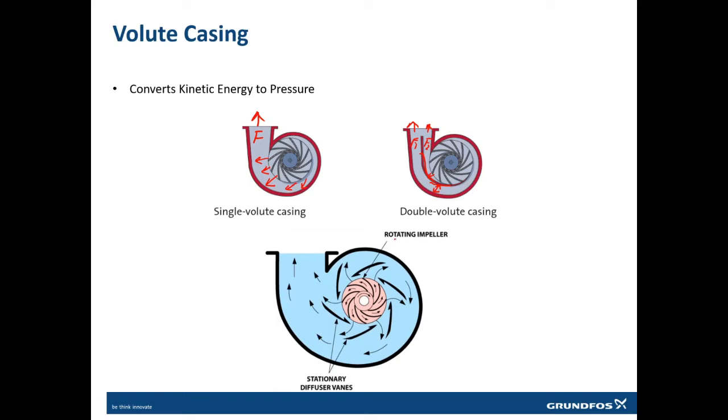Now sometimes there is an additional diffuser. Stationary diffusers are used, like this, or this. The purpose of these diffusers is also the same: to reduce the radial forces on the impeller, and to divide the flow into smaller chunks, so that all the forces acting on the shaft of the impeller are reduced.